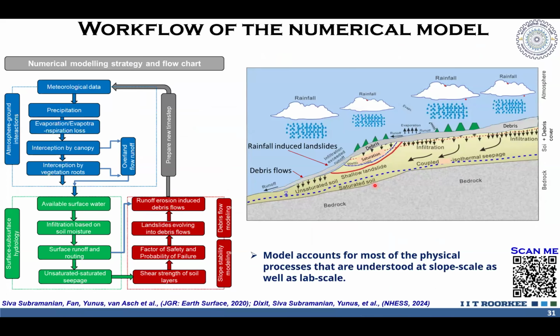So that actually considers the fundamentals of the hydrological process, what we see in the two-dimensional cross-section here, as well as the geotechnical process, provided, as I already mentioned, that as we move across the scale, we have the problem of complexity as well as phase transition and dimension. So we cut across dimension, it is a 1D model, and we cut across phases, it is a single phase flow model. That's the biggest limitation this model has. Provided it can be used for some purpose of understanding or to develop some thresholds for early warning. That's what we would like to see.